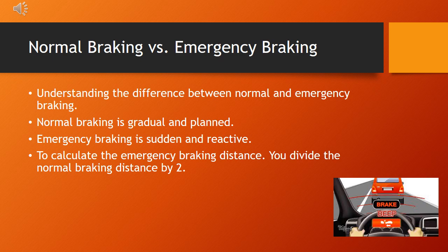In emergency braking, the driver applies maximum force to the brake pedal in a rapid manner. This type of braking is reserved for situations where there is an immediate danger, such as when a pedestrian suddenly steps onto the road or a vehicle unexpectedly stops in front of you. Emergency braking is characterized by a sudden and intense deceleration, which can result in a shorter stopping distance than normal braking. However, it should only be used when absolutely necessary, as it can lead to loss of control or skidding if not performed correctly or if road conditions are unfavorable.